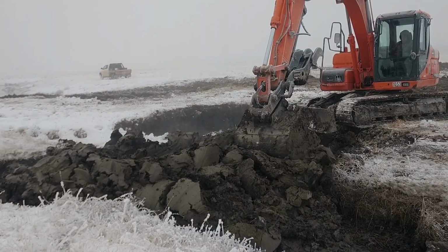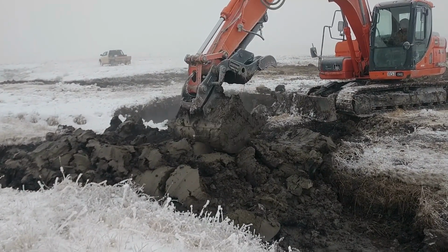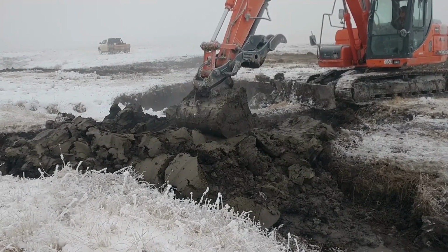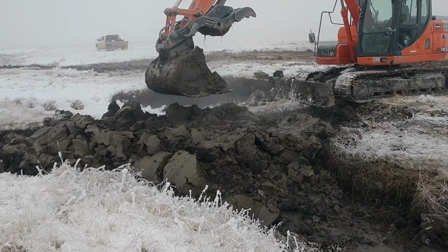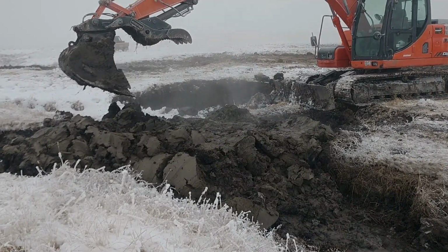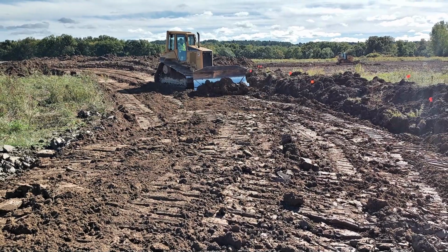The excavator operator is compacting saturated clay soil in the core trench to make another groundwater dam. The soil needed to fill the trench for the groundwater dam is being removed from the wetland basin that's being dug. The operator must be very careful not to get stuck in the mud. This photo shows a different project where a ditch was blocked using a groundwater dam.